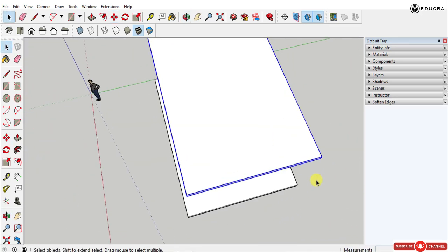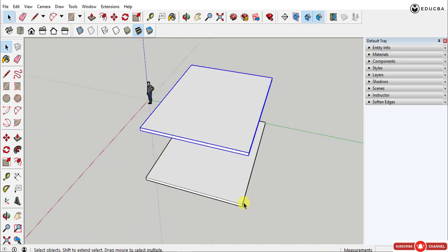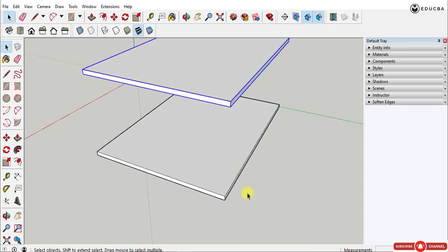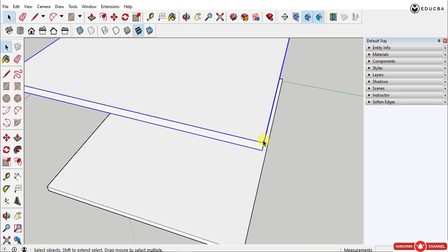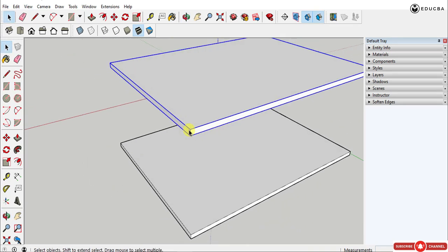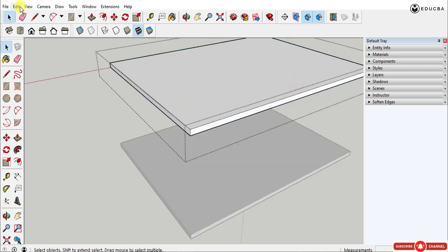Now, when I need to connect them both, I need to make a staircase or steps or any other module that connects both the slabs. Here, if I require, say, 4 feet, that is a 1200 mm length of the width of the slab that is required to make a staircase, I won't be able to connect them both unless I make a staircase.